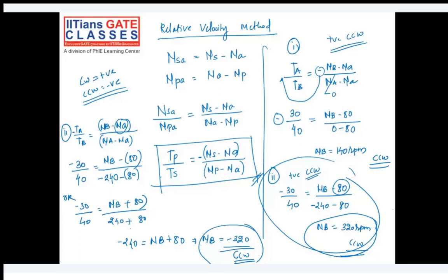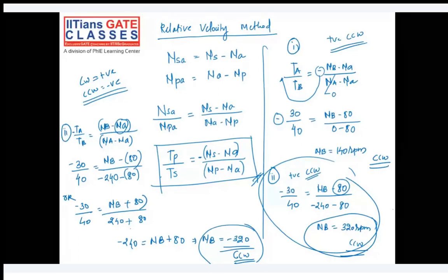In case of intersecting shafts, we can have bevel gear. The bevel gears can be straight bevel gears or the spiral bevel gears. The special types are miter gear and Zerol bevel gears. That also we have studied. In case of skew shafts, when shafts are non-parallel, non-intersecting, we can have a helical gear or the worm and worm wheel.